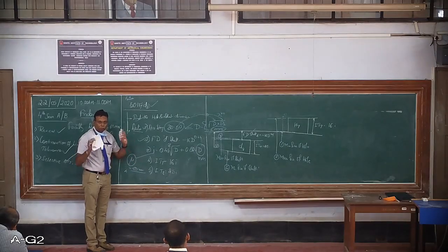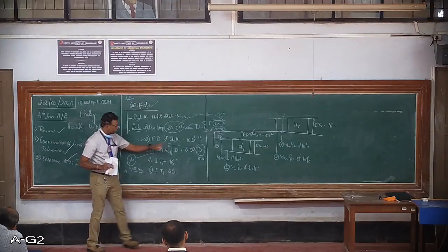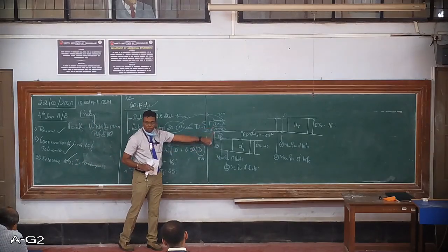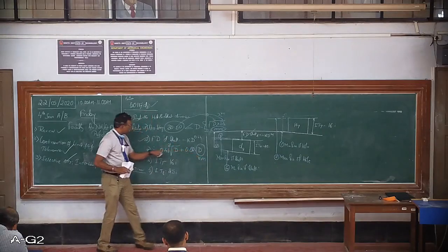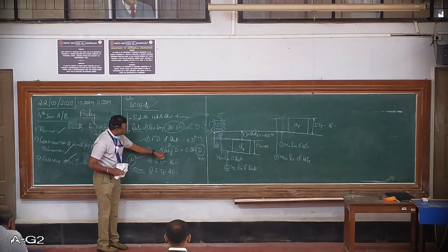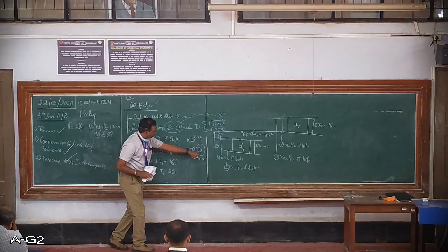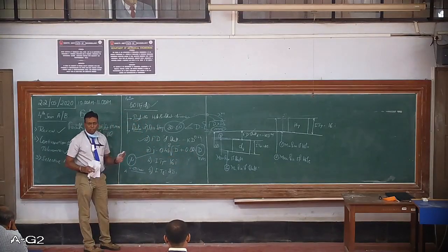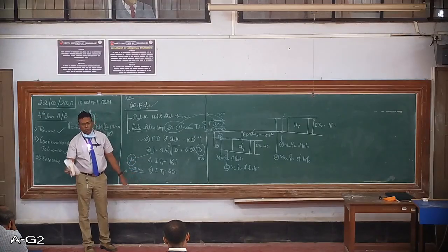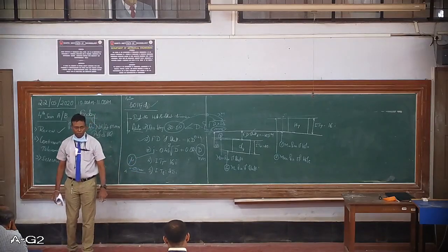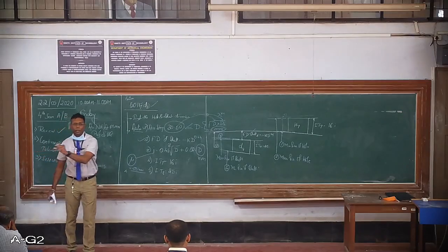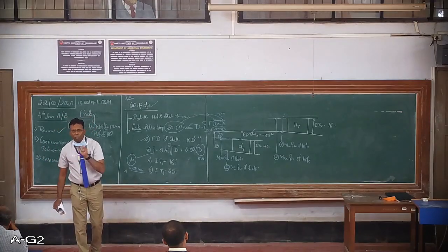Please note, the only standard procedure is to take the D value you get in the previous step and substitute it here. I is equal to 0.45 cube root of D plus 0.001 D, and keep in mind the answer you get is in micron. Later on, you can convert it in terms of millimeters. If you follow this step, it will be of great help during our further numericals or calculations.